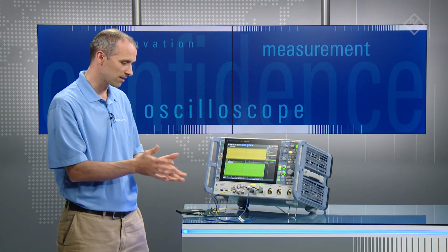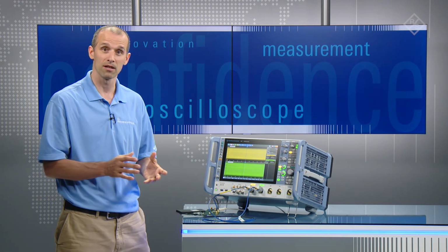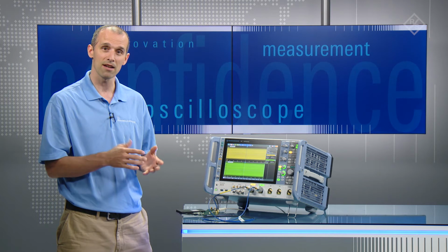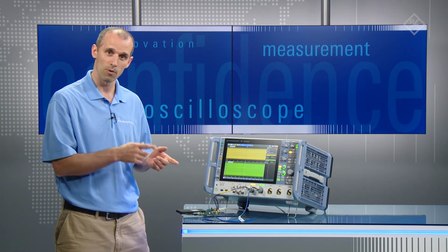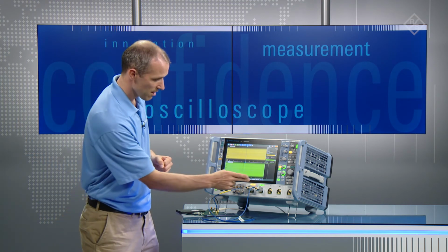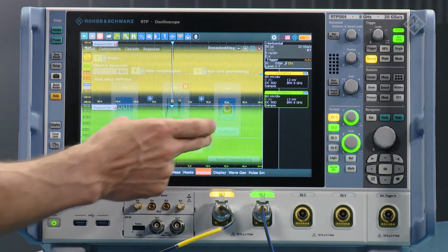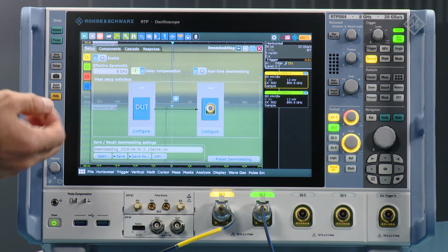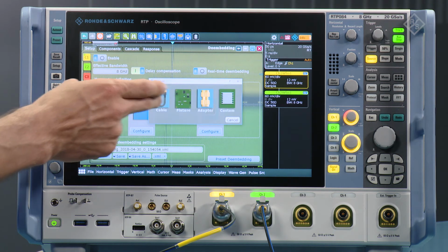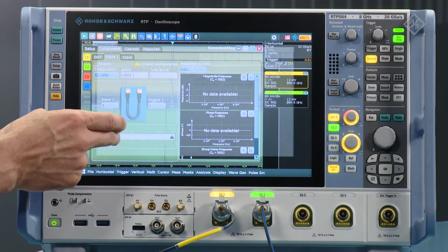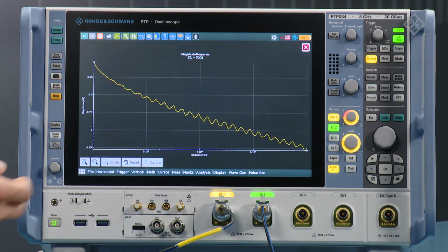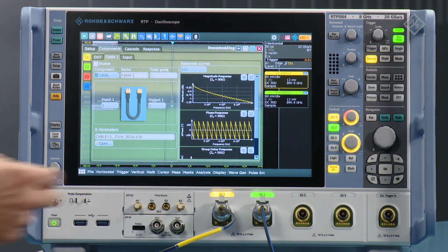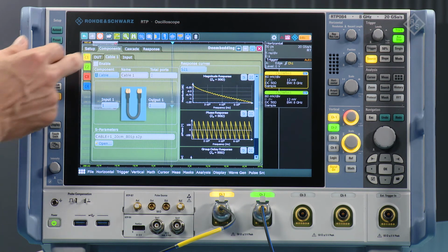Well, if you look at the setup, there is one minor detail. Channel 1 also has some delay through the cable itself, even though it's short. So once we de-embed that cable, we expect both waveforms to be time aligned. So now I'll go back to channel 1, add our cable. Of course, this is the short 20 centimeter cable. If I look at the loss, this is about 1.25 dB out to the bandwidth compared to the 6 dB loss of the long cable.